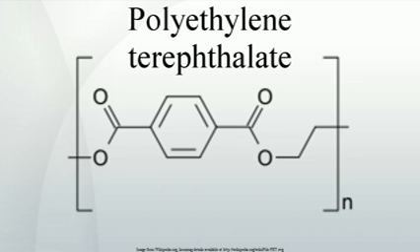Mechanical recycling, or direct circulation of PET in the polymeric state, is operated in most diverse variants today. These kinds of processes are typical of small and medium-size industry. Cost efficiency can already be achieved with plant capacities within a range of 5,000–20,000 tons a year. In this case, nearly all kinds of recycled material feedback into the material circulation are possible today. These diverse recycling processes are being discussed hereafter in detail.